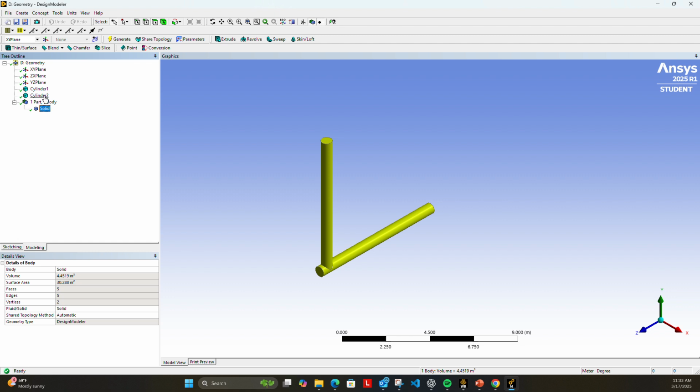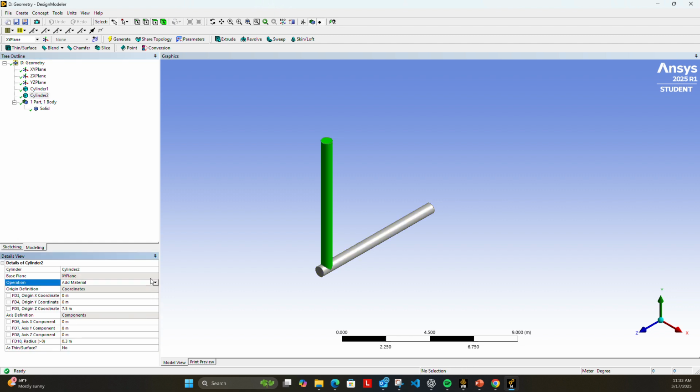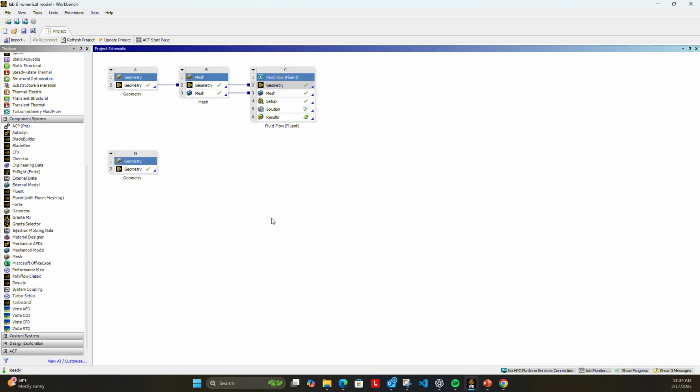It doesn't really matter if we add frozen or add material here. Specifically, we want to essentially adjust the traffic light. This is the base of our traffic light, and the rest of it is going to be left free. So we have to export and import. The export from Fluent and import it to the static structure module, the pressure data we have on this traffic light, essentially. Let me close this and go to the modules again.